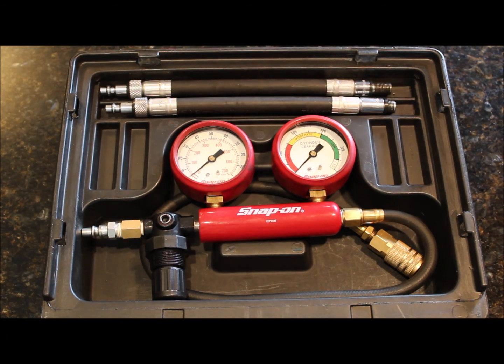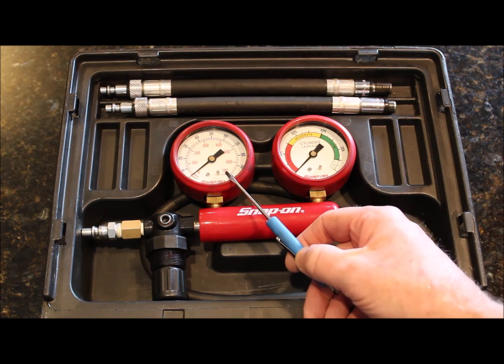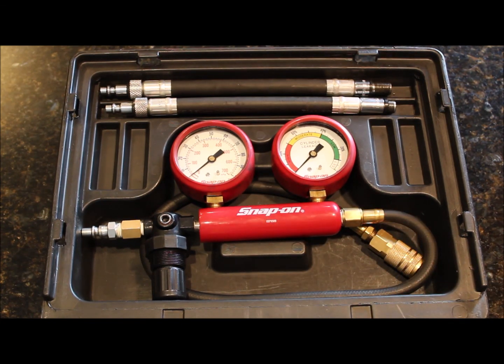There are times, and we talked about this too, when you have a small engine where 100 psi applied on top of the piston causes the piston to be pushed down in the cylinder, which takes it out of the position it needs to be in for the cylinder leakage test. And if you remember, for cylinder leakage, we have to have the piston at top dead center on the compression stroke where both valves are closed, so the cylinder will be sealed up. If the piston gets pushed down in the cylinder, then it's no longer in that position. Air leaks out through one of the valves that's now open, and the test is useless.